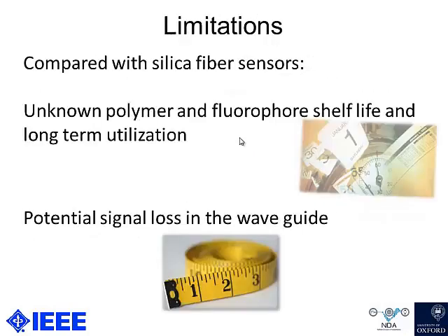Now, in terms of limitations of this sensor at the moment, they're mostly relative to the silica fiber sensors, and they're either unknown or potential. We're working on them. So we don't really know the polymer and the fluorophore shelf life and long-term utilization. We don't know about the potential signal loss in the waveguide, which may not necessarily be an issue in an operating theater where the sensor is only a couple of meters from the recording point, but it may be an issue in other applications where the sensor is much farther away.